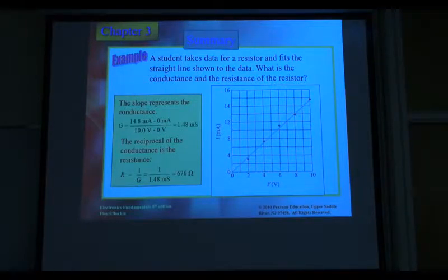Any questions? So in the lab, if I give you a resistor and you cannot read it, you cannot measure the resistance directly, you can use this way to measure it. You measure the current-voltage curve to calculate the resistance and also the conductance. Question?